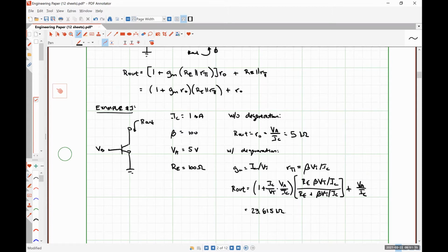Well, that emitter resistor is also carrying the current IC, or actually it's carrying (1 + 1/beta) times IC. And so we are going to experience a voltage drop over that emitter resistance, which is going to limit the output swing of our amplifier. The maximum value that our amplifier could possibly output is VCC. The minimum value would be 0, but we're shifting everything up by the voltage drop over our emitter resistance.